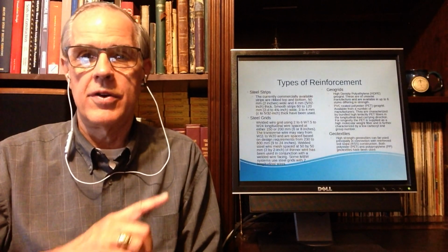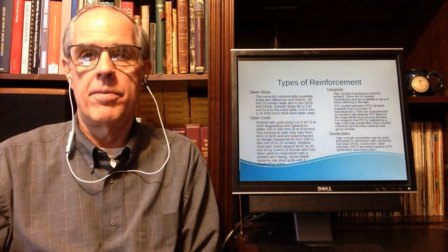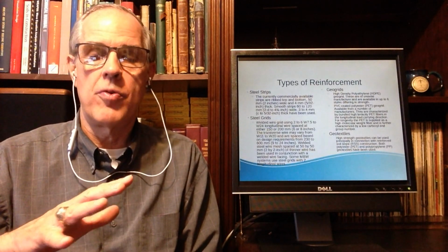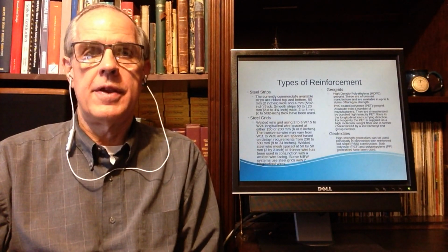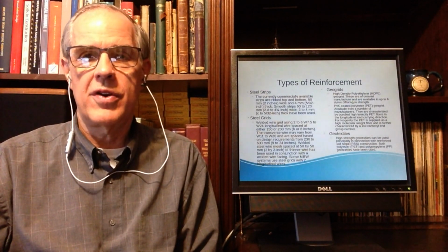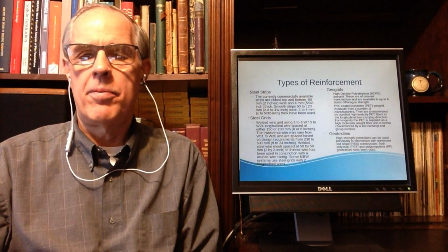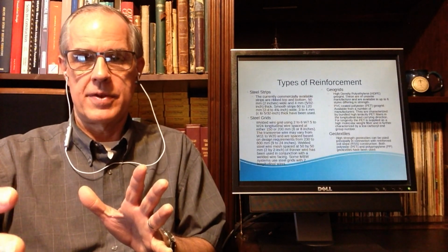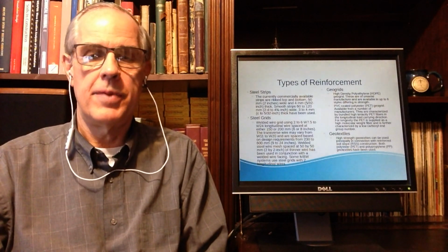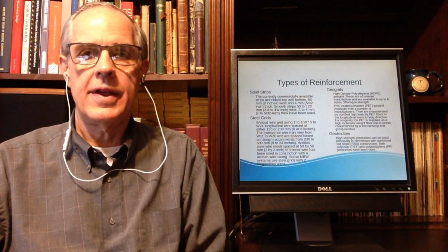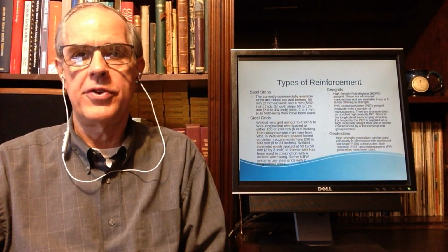On the other hand, geogrids and geotextiles are different kinds. They're probably newer kinds, and they're always coming up with new formulations. The big disadvantage of geogrids is twofold. One is creep. All plastic materials are subject to some kind of creep, where over time they will grow, so to speak, under tension. The other thing, but it's not an issue with MSE walls, is UV.